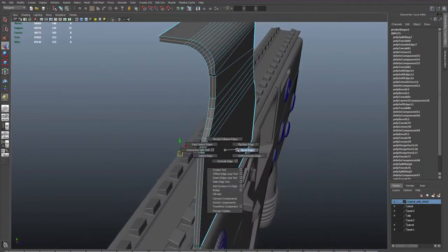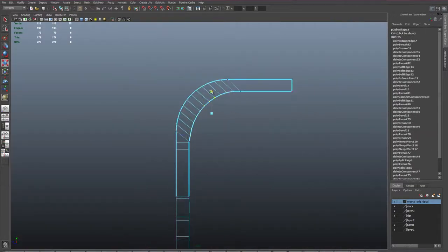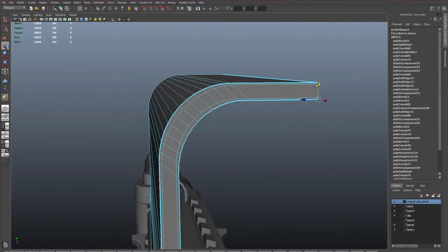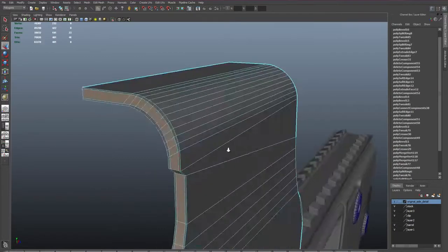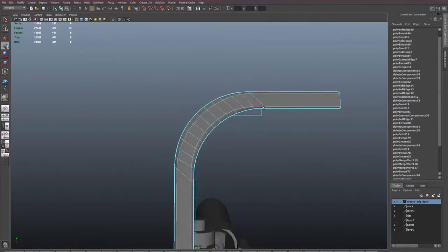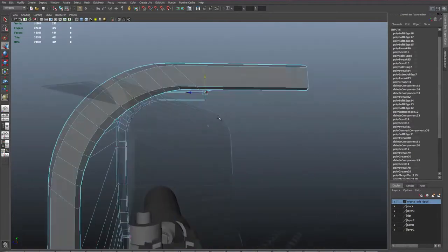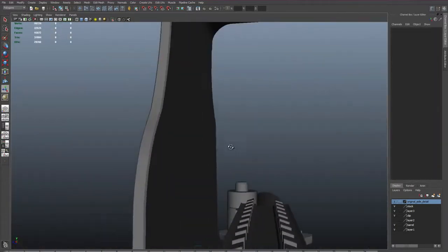And then the next thing that I'll do is I'll cut a line down the center of each side of the object, and I'll bevel that line, and I'll just take the resulting row of faces and pull it straight out. And in this fashion, I'll create kind of that beveled edge that I need. Doing it this way gives me a little bit more control than actually beveling it because the bevel tool doesn't work that great on strange corners and curves like I have on this object.